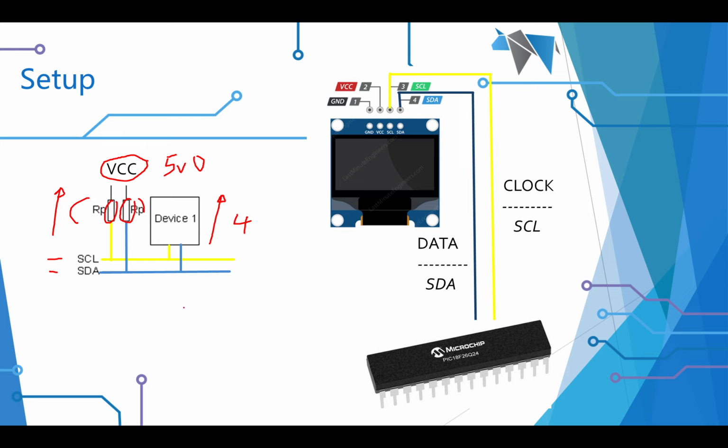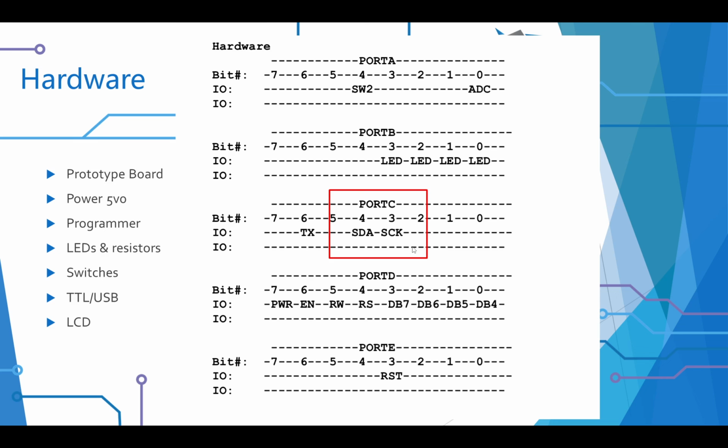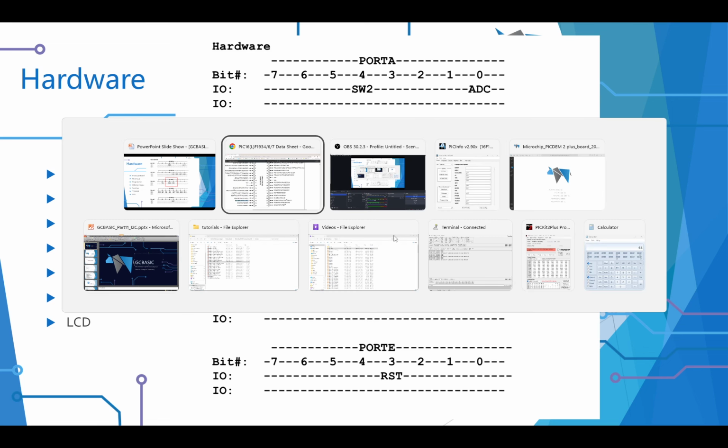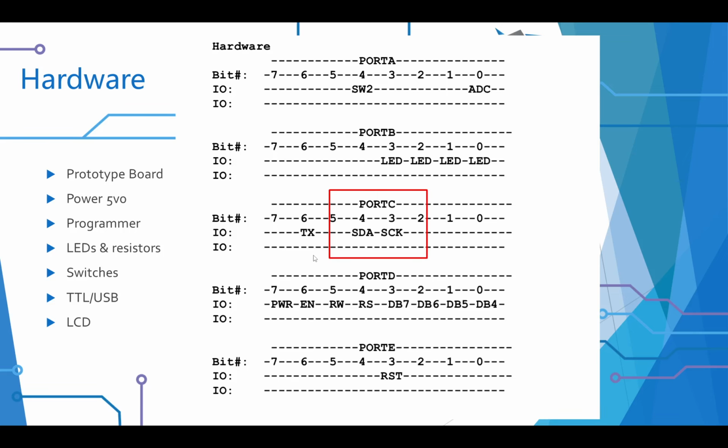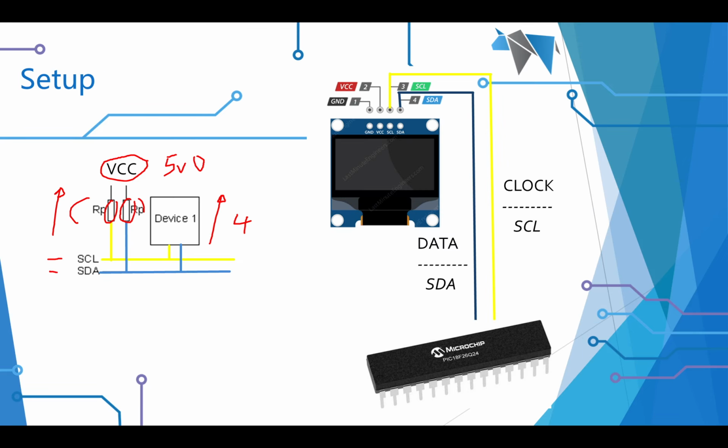SCL, look. Let me go back to my PowerPoint. That is incorrect. I will change that before I publish, okay? All right. It should be SCL. Then those lines will be connected into your I2C devices. So yellow, I typically use yellow for the clock line, sorry, and the blue for the SDA. That is important. No pull-ups, no worky.